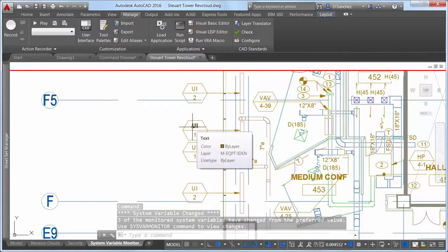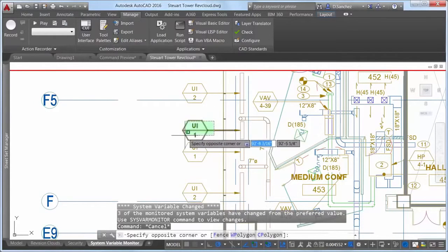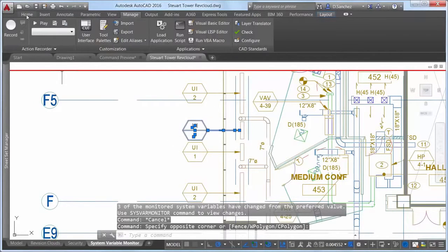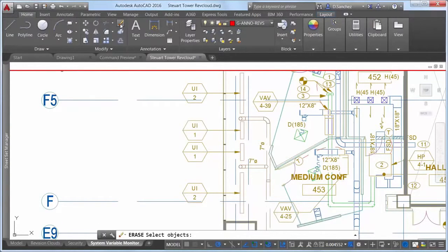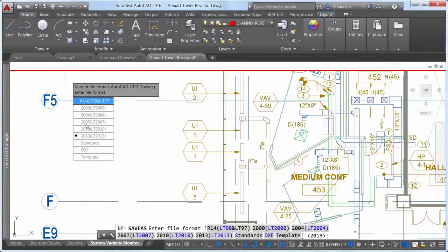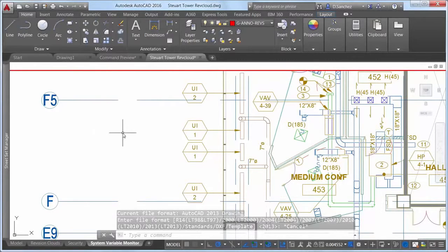When you double-click on text, it doesn't open the text editor. You select the seemingly troublesome objects to try to erase them, but they won't go away. As a precaution, you try to save the drawing to a different name, but the familiar Save As dialog box won't even display. Your drawing isn't corrupt and your software isn't broken. That handy little Lisp routine that you ran happened to change a few system variables and didn't restore them to their previous and familiar behavior.